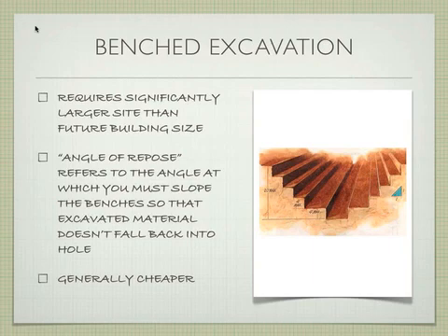Okay, so what's called the angle of repose, right, is the angle if you drew a line across each of these points as it goes down to the base. That's called the angle of repose, and that's going to respond to the type of soil you have. Right? If you have sand, cohesionless soil, that angle of repose is going to be much flatter. Does that make sense? Right? If you have clay, it can be much steeper. So that's going to vary.